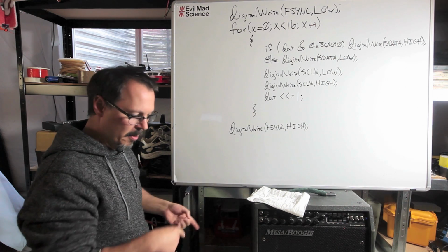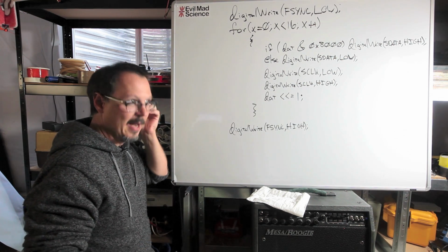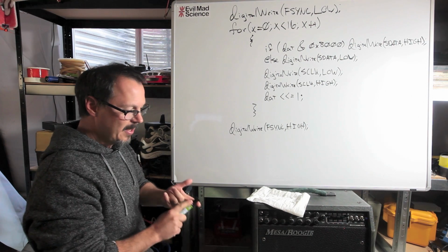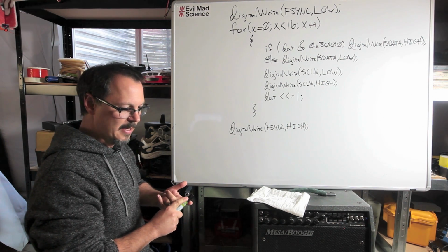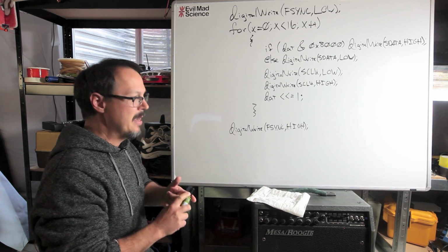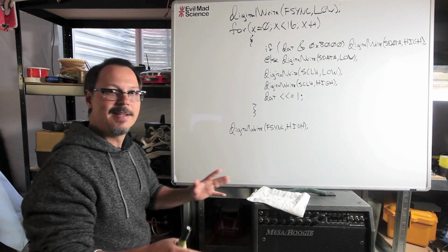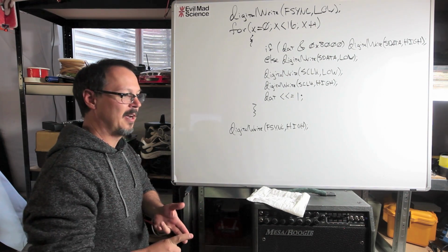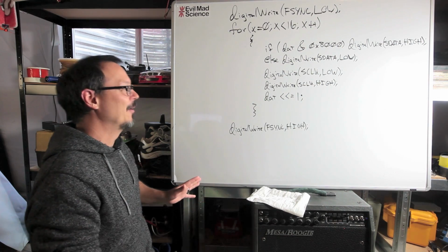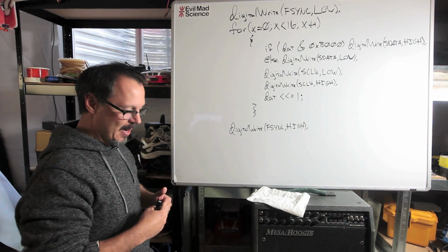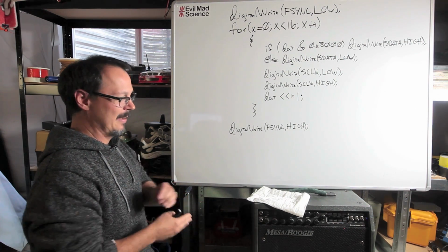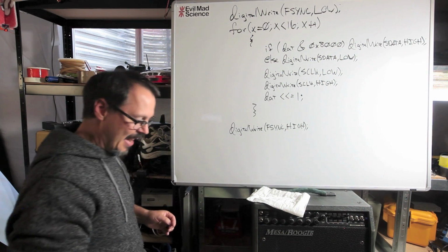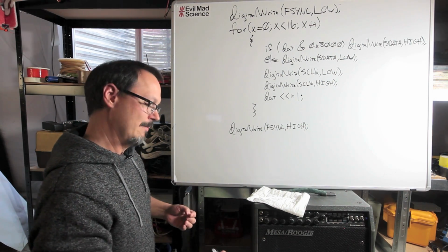Now, if you invert that and you take the period, it's like 62.5 nanoseconds? That's right. What that 62.5 nanoseconds means is nothing gets done in less than that amount of time. In fact, it usually takes more than one clock cycle to do anything in a microprocessor. So as my upper bounded limit, nothing's gonna get done faster than that. I know that, that's an absolute. It's not an accurate number, but I know nothing's gonna be less than that.